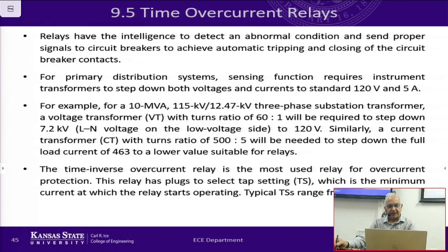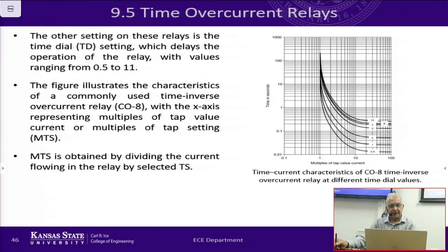So that's the advantage of digital relays, because they have more flexibility in terms of settings. So you have a tap setting that ranges from 1 to 12 amps, and the relay has another thing associated with it, which is called the time dial. And I think in India, it is called the time multiplier. Is that right? Yes. Okay, so this time dial is the same as time multiplier. That was plug setting.